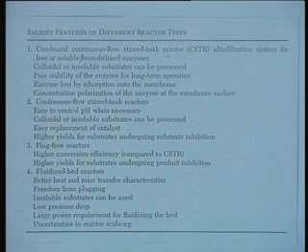Now, of course, such reactors have been very poor in terms of long term operations, mainly because of the adsorption of the enzyme onto the membrane surface. Most of the membranes provide a good adsorbing surface, and the enzyme gets adsorbed onto that, and the reactor performance is deterred during continuous use. Of course, concentration polarization and all the limitations of an ultrafiltration system will also be associated here. The reaction system will have to face all the problems like concentration polarization, and unless those are taken care of, the reactor performance will be adversely affected.